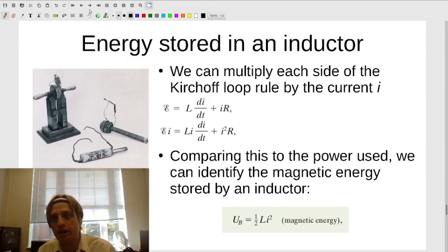So the rate at which it dissipates energy is the power, which is I squared times R, and that gives you the power that's being dissipated through that resistor. It's getting hot, or letting off light if it's a light bulb or something like that, at a rate in watts, which is joules over seconds. Now, what's interesting is that an inductor also has some relationship to energy in the circuit, but it's not dissipating energy. It's just holding on to some energy related to the amount of magnetic field that it generates.